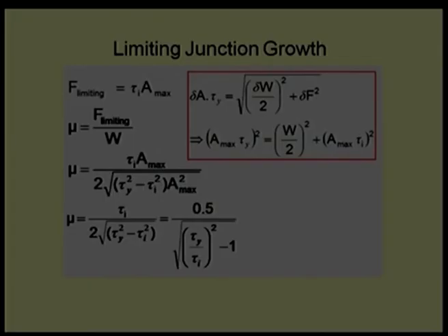That is the difference. If the interface fractures at the value of the shear strength of the material, then the coefficient of friction will be very, very high. However, if the shear strength of the interface is very low, the coefficient of friction will be lower, and this is the reason why we provide lubricant. With lubricant at the interface, the interface shear strength will be almost negligible compared to the solid material strength. Just to get a feel of that, we did some calculations.